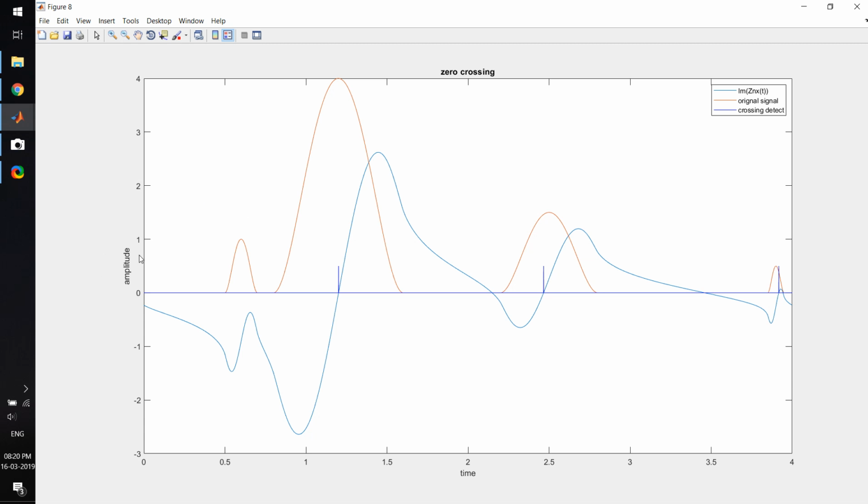So you can see that the Hilbert transform has, although this kind of shape exists, which should have been quite close to 0 for detection, but because of this bigger pulse, it has got suppressed in amplitude or gone below 0 value. As a result, the 0 crossing detection method does not work, although it quite accurately determines the position of the peak for the bigger pulse, but for the other pulses the position gets a little bit distorted, as you can see for both of the cases here.